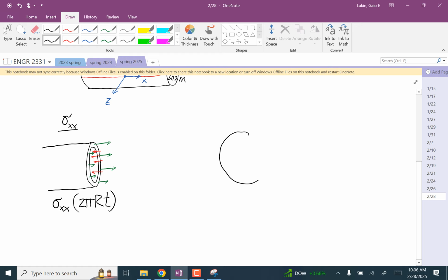Yeah, exactly. So what's the area of that ring? If it's finite thickness, then it's complicated. Really the way to do it is calculate the outer area and subtract the inner area. But if it's an infinitesimal thickness, you can disconnect the two ends and straighten it out into a long skinny rectangle. And we're assuming thin walls, so we're going to make that assumption here.